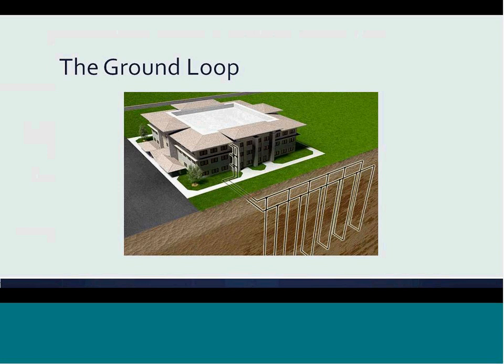Laying out the system requires knowledge of the requirements for proper flushing and purging of the ground loop, in addition to understanding the impact of the ground loop and piping design on pumping energy.